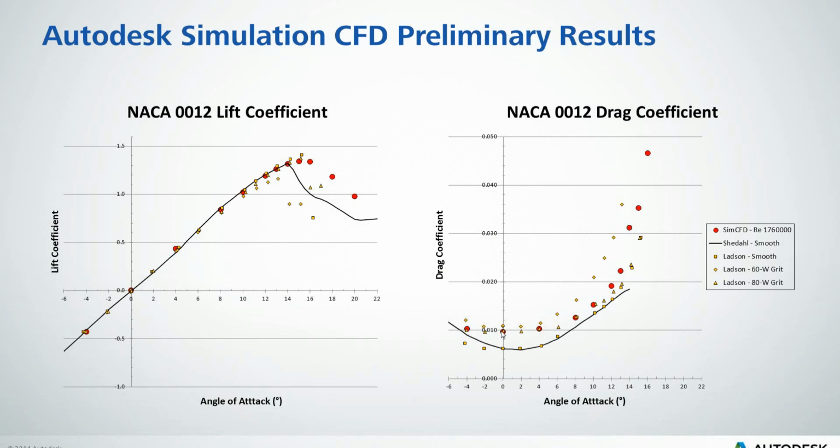And this has to do with the SST turbulence model. If you look at the forum post, actually, Omkar made the comment about how the SST K-omega turbulence model is basically an always-on turbulence. It doesn't have a laminar state where it can really solve for 100% laminar, where if you could, then you could actually approximate those smooth results, that bottom trend, much more accurately. Okay.